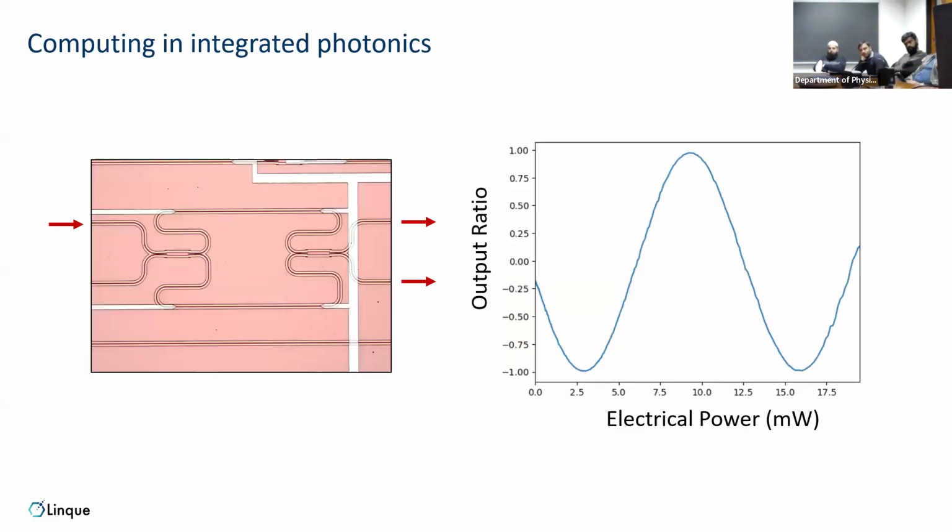And this is essentially how it looks if you use it, right? These are thermo-optic phase shifters on top, basically just very narrow metal wires. Narrow because then the resistance gets high, so you dump all of the power into that specific area and it heats up. And then in the output splitting ratio, you can see basically the tuning of the Mach-Zehnder.